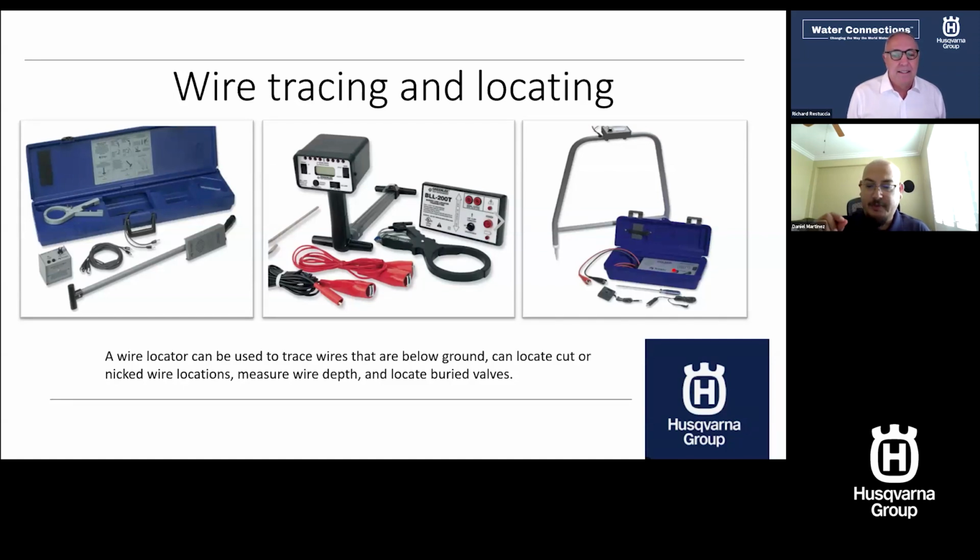You touch on a very important thing there, Richard. Whenever I've gone out to do troubleshooting, ask questions. What kind of work have you done? We had the gardener digging around. Well, my timer's right next to it, my valve's on the other side of my planter. Maybe they hit a wire, right? Oftentimes it's a different trade. The poor concrete guys came in, they excavated a little, and nine times out of ten, they're not going to tell you if they hit a wire. So then you're stuck trying to locate those wires buried below ground, and these are some of the tools available.